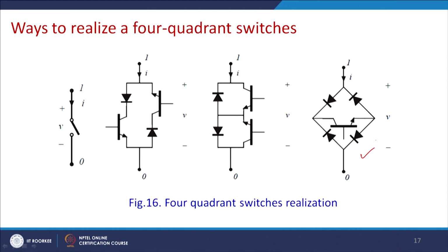So, for this reason there are a few realizations of this circuit. The voltage and current are required to flow between point 1 and 0. So, this can be realized by many switches. A normal mechanical switch is automatically of this configuration. Let us see how this can be realized by semiconductor switches. So, the rightmost circuit we shall take first. In this circuit, if V1 is greater than V0, then the path of the current will be through this.